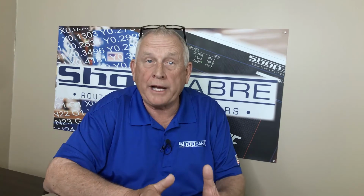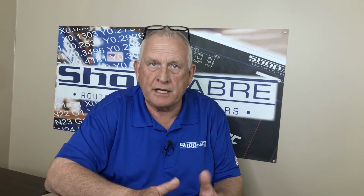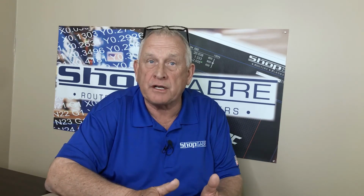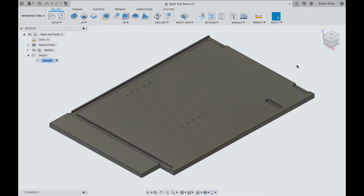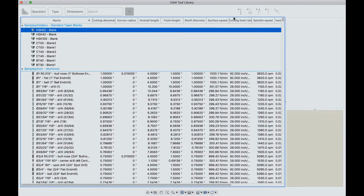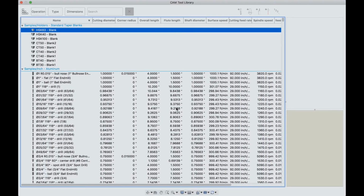Before we start creating tool paths, let's take a look at the tool library in Fusion 360. It makes sense to create this ahead of time because it makes you more efficient and leaves less chance for error. This is how mine is set up. To access the tool library, click here, and you'll notice there's lots and lots of tools, and a lot of them have nothing to do with what we do material-wise. So I would recommend that you do what I've done.